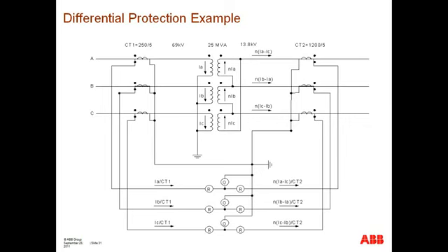Again, the sudden pressure relay is really considered a unit protection. Could it be triggered by an external fault? Well, let's explore the principle of how it works. It's essentially monitoring a rapid rise of pressure inside of the transformer. That rapid rise of pressure is usually going to be the result of oil breaking down inside of the tank, which in turn decomposes into gas, which in turn raises the pressure inside of the tank. That sequence of events can only occur if arcing occurs inside of the tank of the transformer, thus indicating that an internal fault exists.